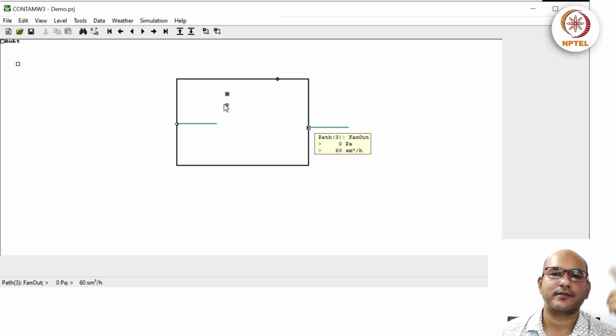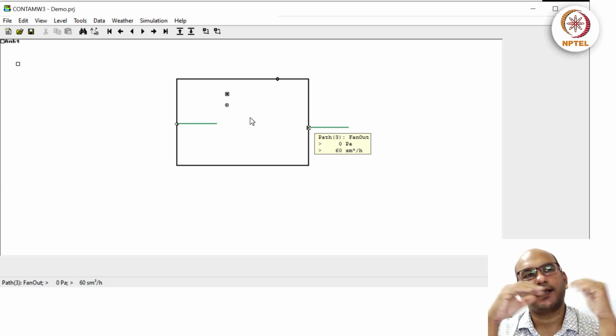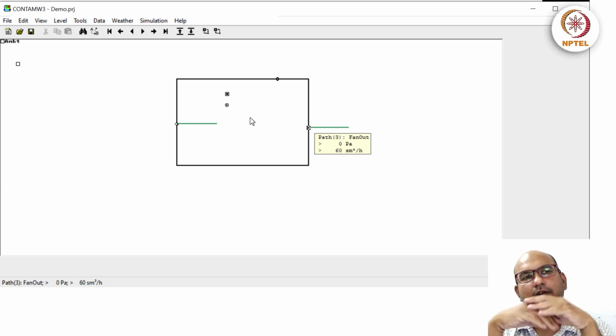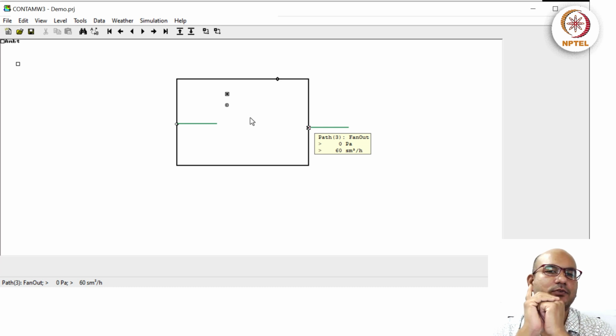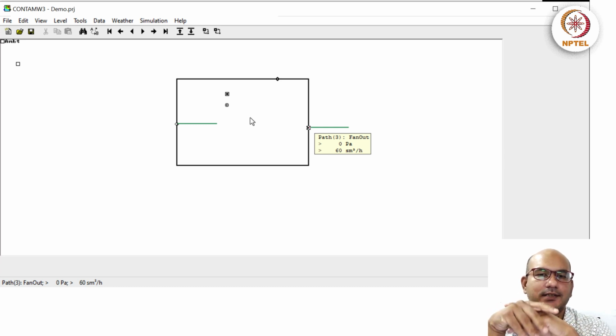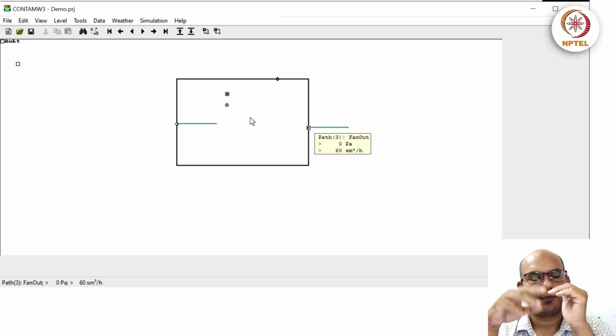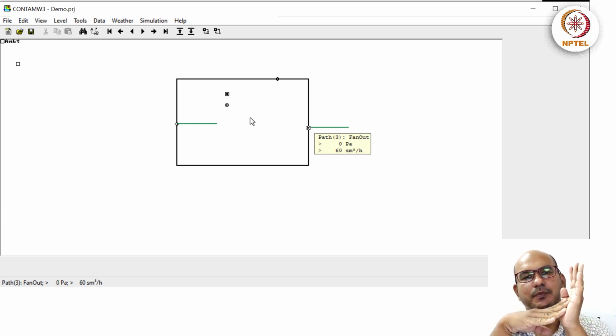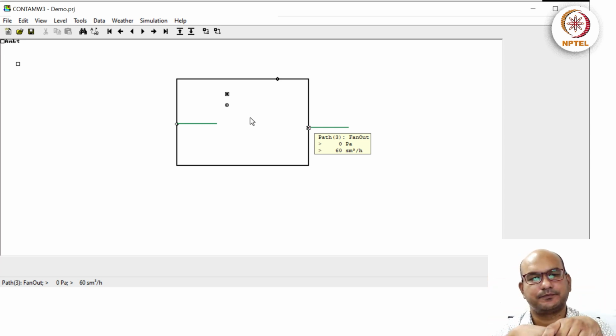But now we have the extra source. So now in addition to the ambient air, we have an extra source inside. That means the extra source starts at time 0. So at time 0 we have ambient air coming in, plus the person is also giving out CO2. So we expect the slope to increase sharply, and we expect the steady state to be higher than 400 ppm, which was derived when there was no occupant.